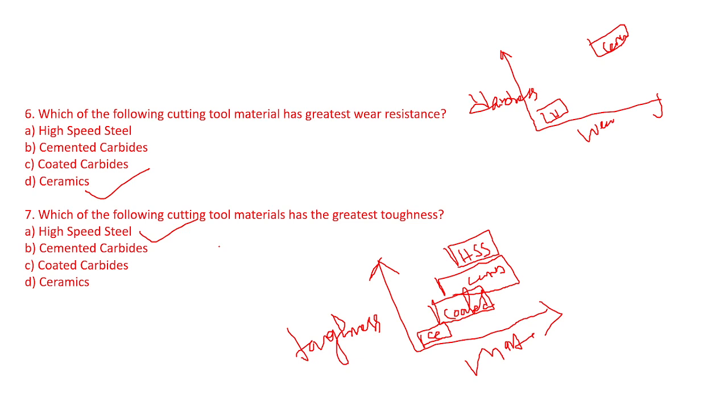So what is the advantage of using ceramic materials? It actually revolves around ceramics' greater ability to withstand much higher temperatures than tools made from carbide or high speed steel. That's the reason. In terms of hardness, if we compare, it has the greatest hardness compared to other materials.